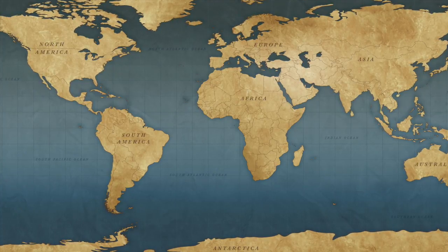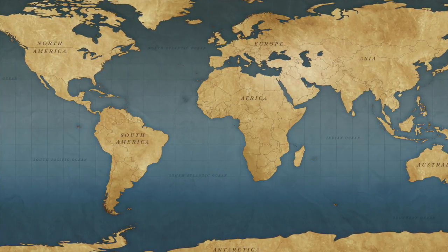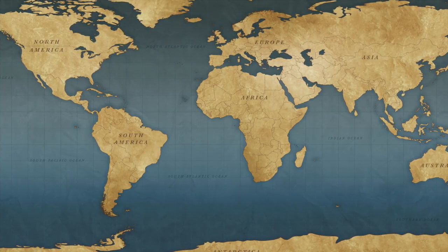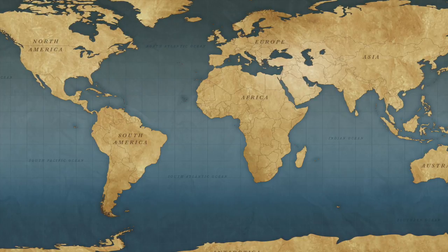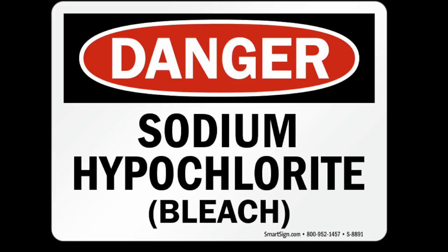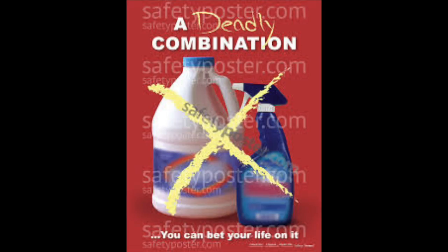Number 1, engineering controls. Number 2, administrative controls. And as a last method of recourse, personal protective equipment. Engineering controls include the following. Eliminate or minimize the hazard. Designing the facility, the equipment, or process to remove the hazard, or substituting processes, equipment, materials, or other factors to lessen the hazard. Enclosure of the hazard using enclosed cabs, enclosures for noisy equipment or other means. Isolation of the hazard with interlocks, machine guards, blast shields, welding curtains, or other means. And removal or redirection of the hazard, such as with local and exhaust ventilation.